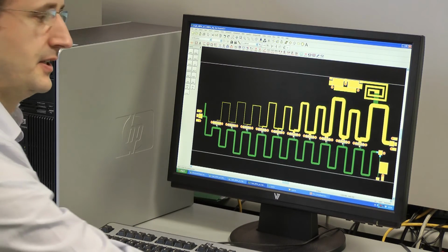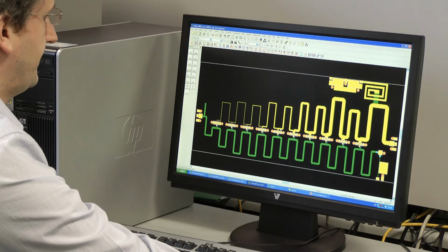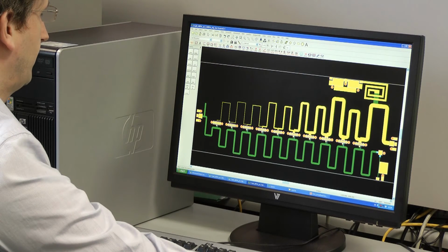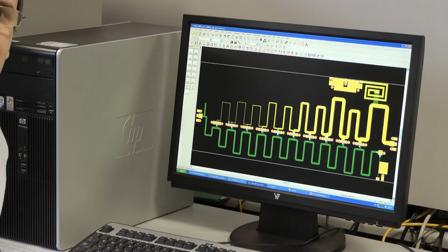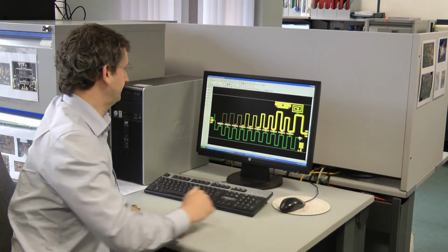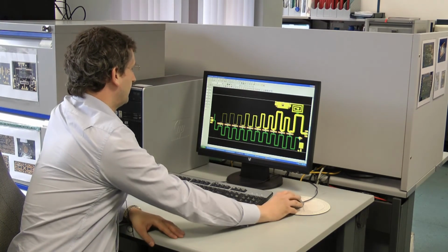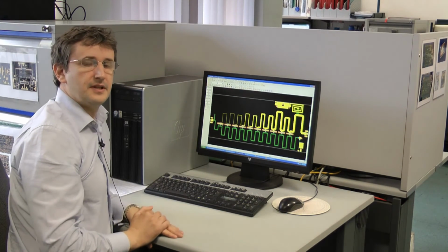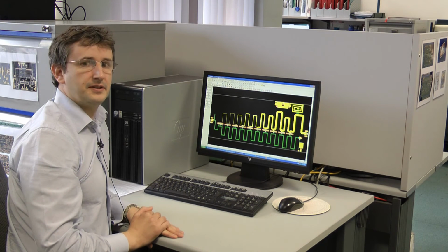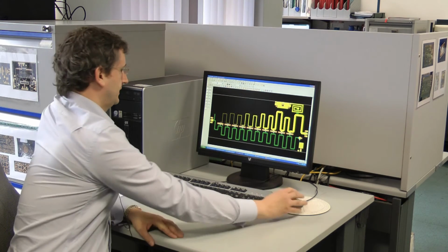What we're trying to do is ensure that each device works into this optimum load for power. In doing this, the microstrip lines in the drain line get progressively thinner and thinner. There is a limit on how thin we can make these microstrip lines. For this reason, this far device near the input is made larger than the other 9 devices.